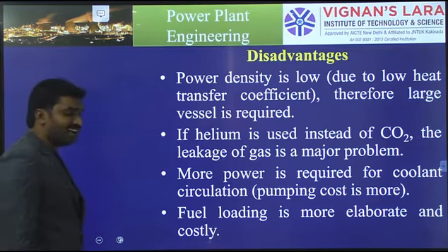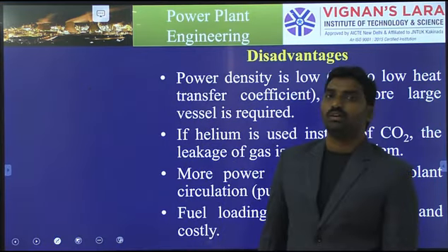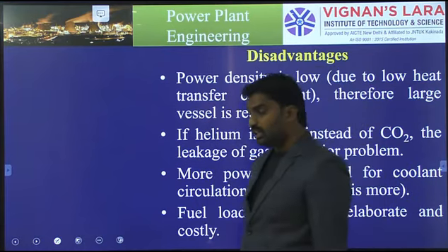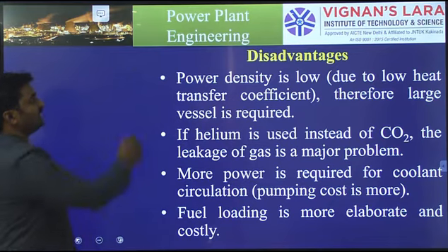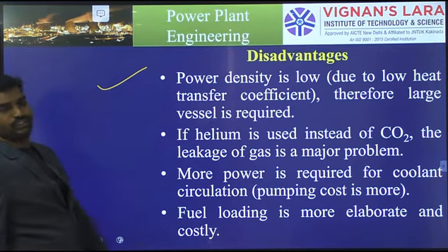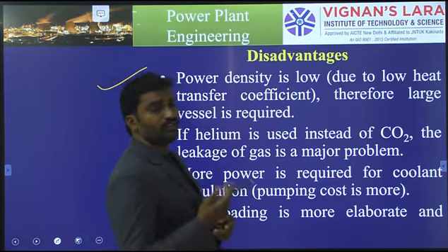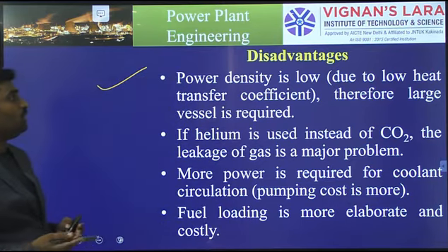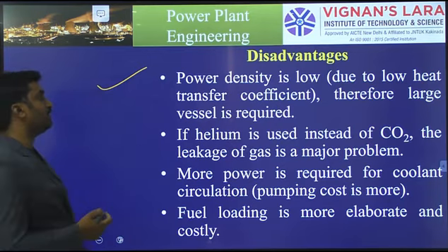And it has some disadvantages. What are the disadvantages of gas-cooled reactors? The main disadvantage is that the power density is very low compared to water-cooled reactors, due to the lower heat transfer coefficient. The gas has a very low heat transfer rate, and whenever the heat transfer rate is low, the power density automatically reduces. Therefore a large vessel is required.